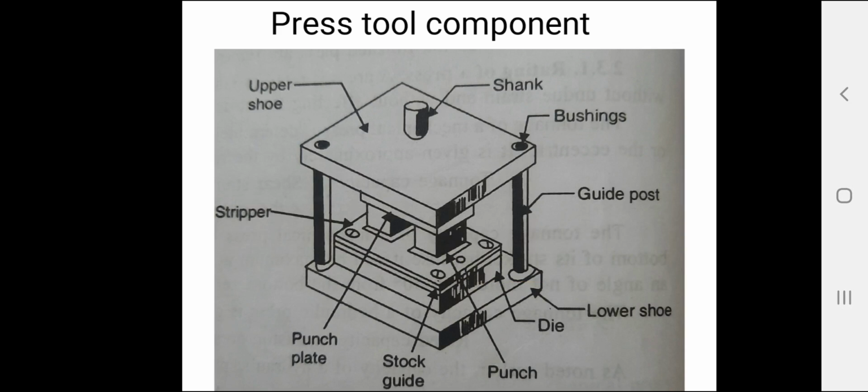What is a cutting die? Cutting dies are used to cut metal. They utilize the cutting or shearing action. The common cutting dies are blanking dies, piercing dies, perforating dies, notching dies, trimming dies, shaving dies, and nibbling dies. The second type of dies are forming dies. These dies change the appearance of the blank without removing any stock. These dies include bending dies, drawing dies, and squeezing dies.